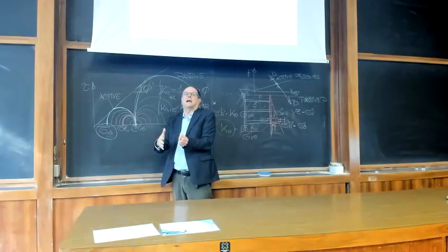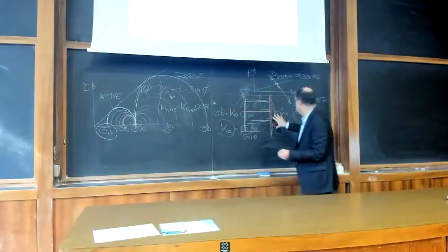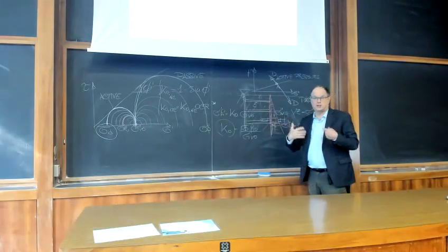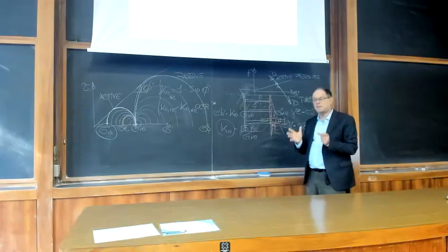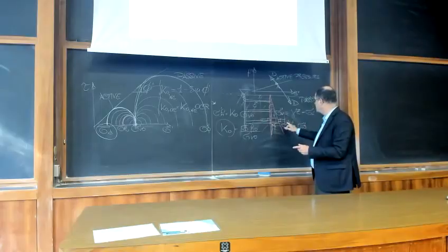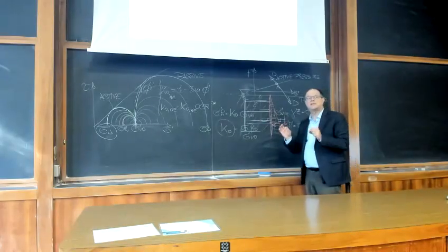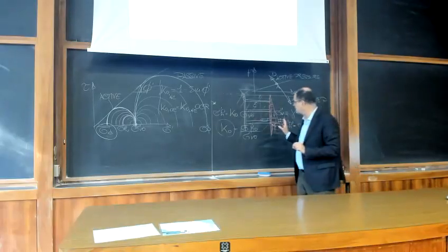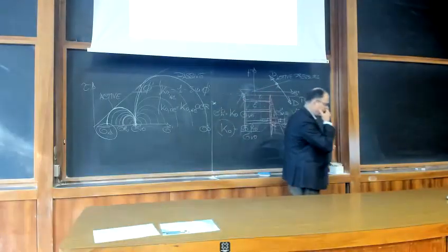And we typically allow that at failure in order to be able to design the wall with a minimum force and not over-design your wall. But never forget that the basic assumption to use the active pressure is that you are using the minimum horizontal force that the soil is able to act on your wall. This is a very important point.